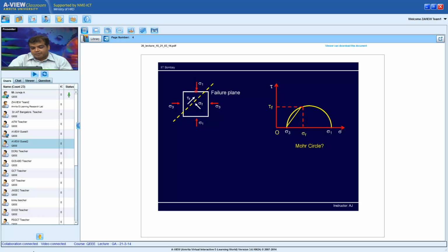In other words, if I recall my Mohr circle and plot this in terms of the Mohr circle, I have the vertical axis as tau, horizontal axis as sigma. And remember, sigma 1 is greater than sigma 3, so that's the Mohr circle for me, although I have plotted a semicircle. I have carried this broken line parallelly and replotted it such that it originates from this pole. Remember, this point is the pole which coincides with sigma 3 only for this condition.